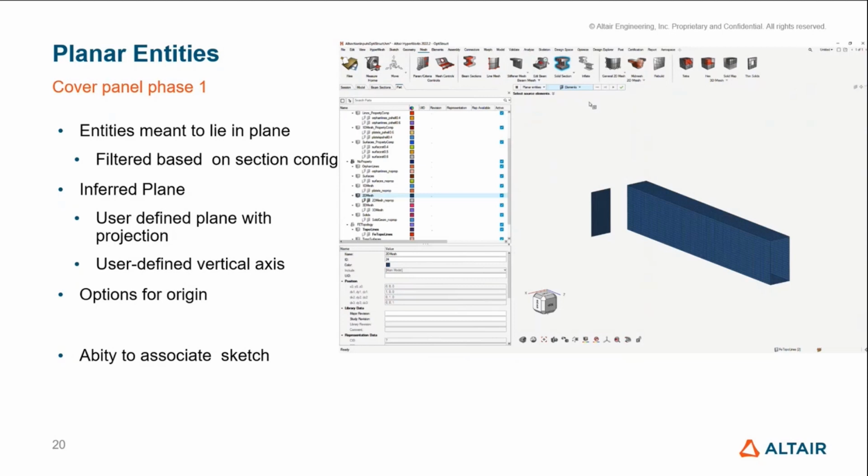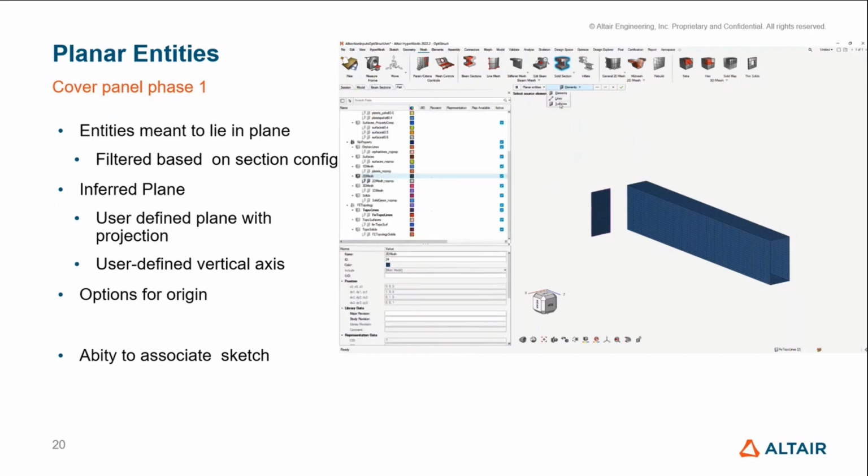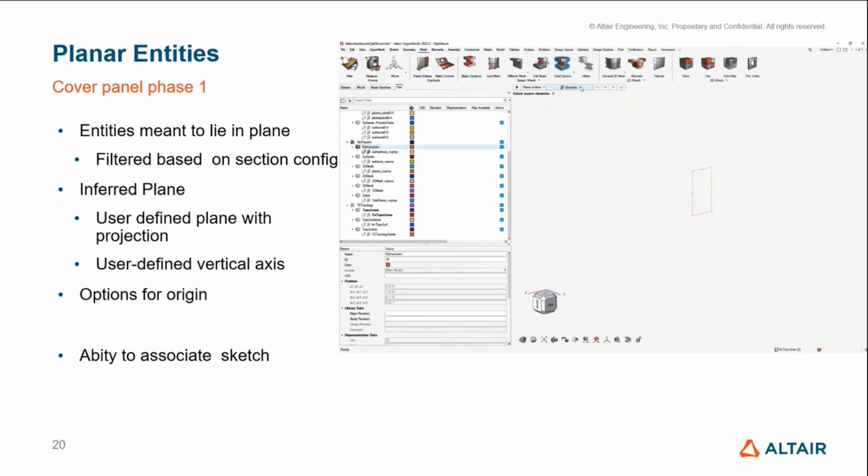By defining a point at any location, here we just continue with a solid from shell. It gives provision to get the moment of inertia at that particular local system. Usually the moment of inertia is calculated against the centroid, and that's what the properties are using. But if you want to know it at a special point, then beam section already outputs the value at the origin of the system.